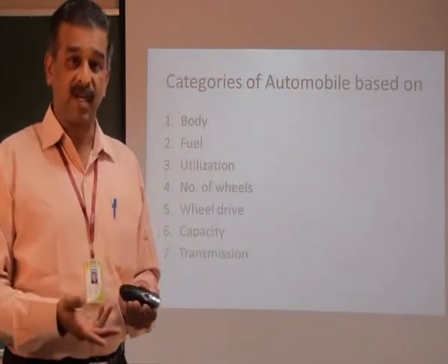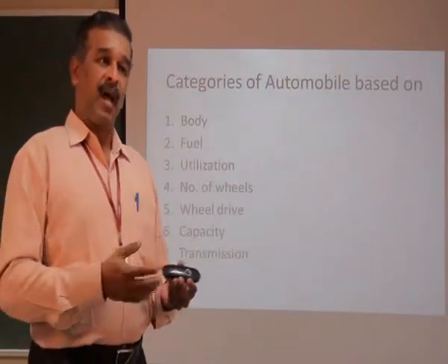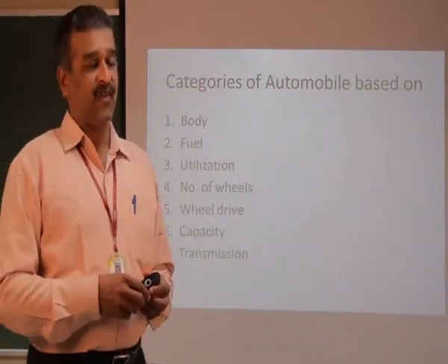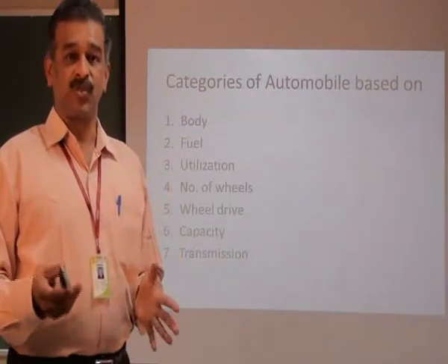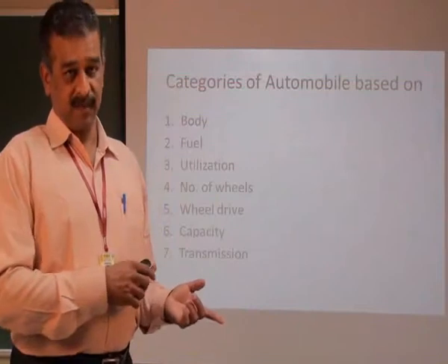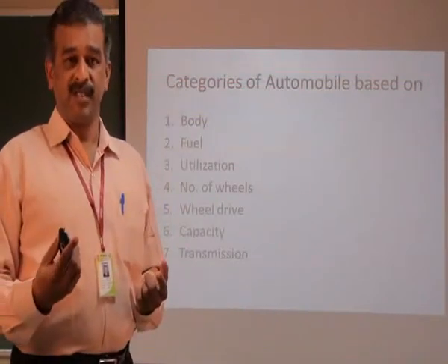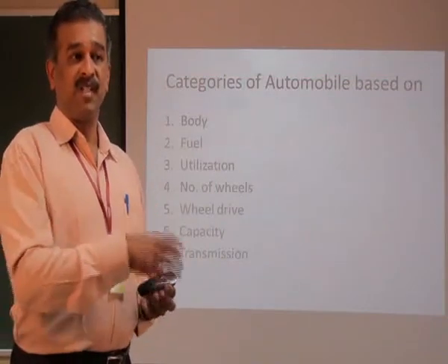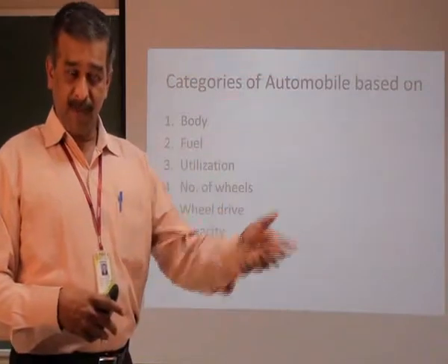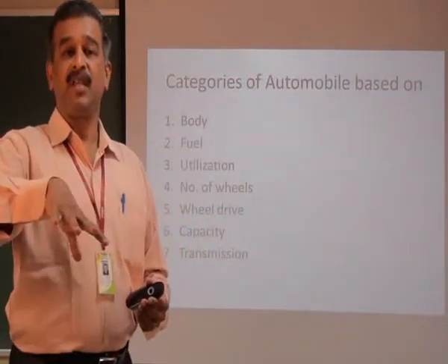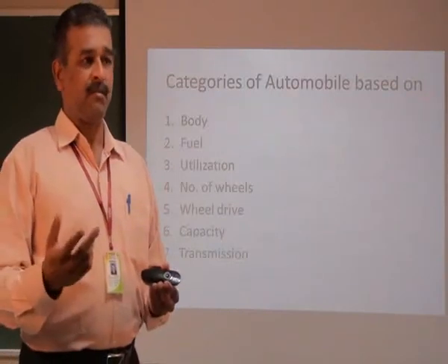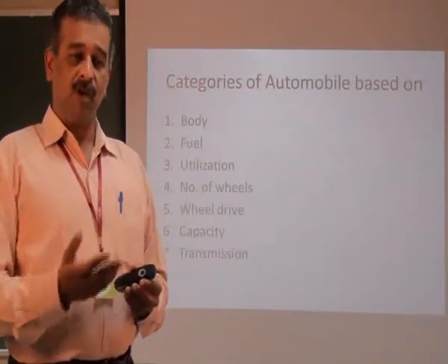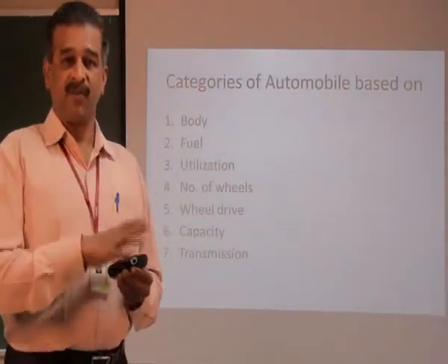That's why most of the modern cars are front wheel driven vehicles. And in olden days when it was invented, it was rear wheel drive. The back end of the vehicle will have two wheels. Those two wheels will be propelled by the IC engine. So when it is a rear wheel drive, that drive will get the power from the engine which is mounted at the front. Through the propeller shaft it will come and it will be driving the rear wheels. So due to that many transmission losses happen. When it evolved, they shifted from rear wheel to front wheel drive.